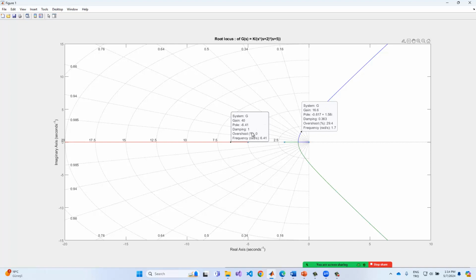This is the damped response of your system in here. See that if we use the root locus, then we can evaluate the whole system in terms of the damping ratio, overshoot, or the settling time of your system for a given different gain, right?